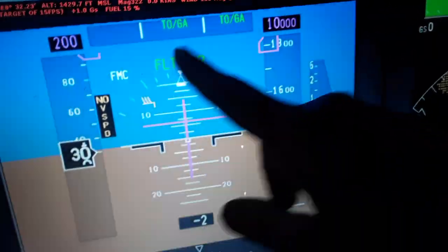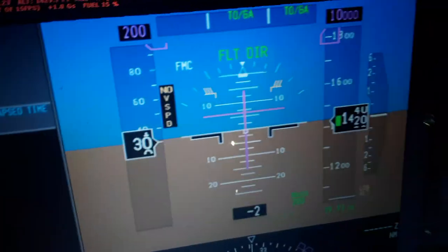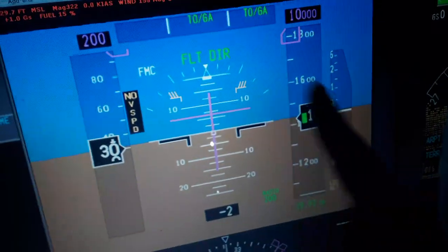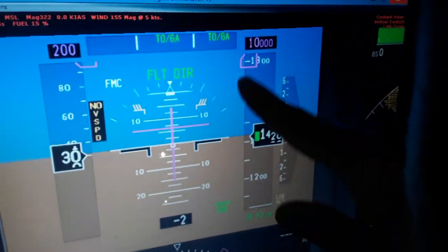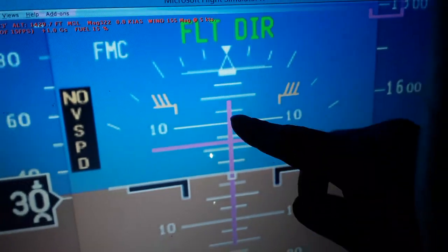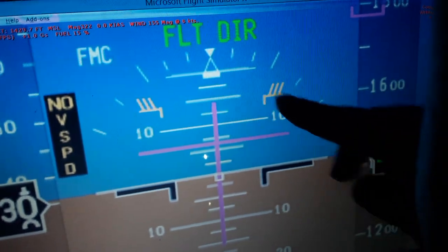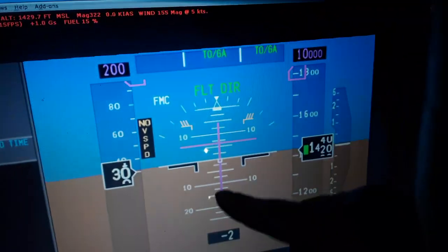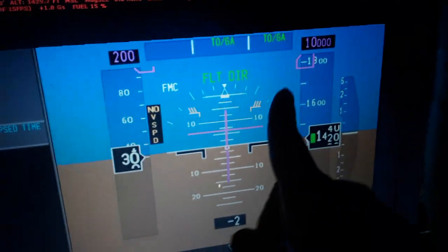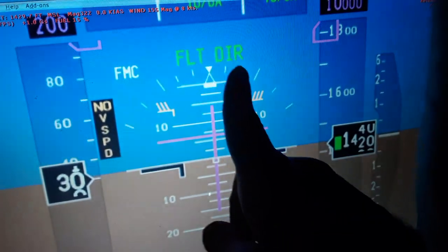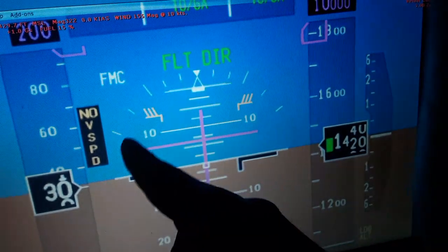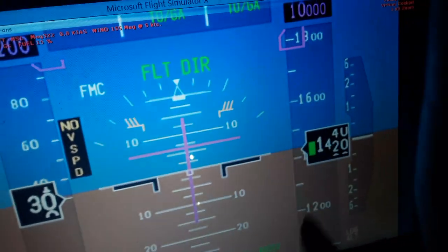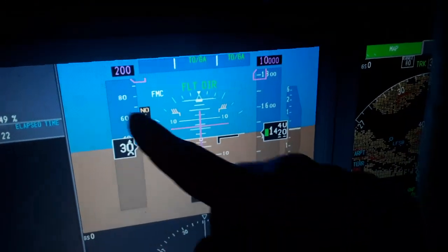So we keep talking about this system. You can see the artificial horizon, the pitch ladder, it decreases here, and the bank angle, vertical rate of climb descent, barometric altitude above the sea level with this barometric pressure. So you see 2.5 over here, 5, 7.5, 10, 12.5, 15, 17.5 to decrease for pitch up or pitch down. And the bank roll, the bank turns over here in the air. You can see like 5, 10, 20, 30, 45 degrees in turns left and right. So you have also the airspeed.